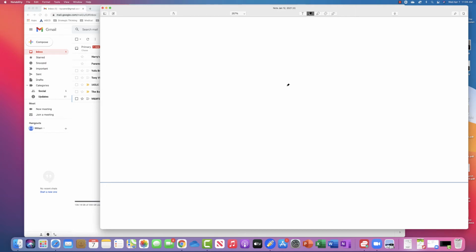Okay, let's move on to number 17. And the key equation that you need to know for these problems is the terminal voltage, that which you actually realize from a battery, is equal to the internal EMF of the battery, which is the total voltage in the battery, minus the current times the internal resistance in the battery.